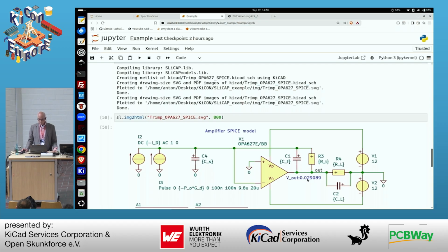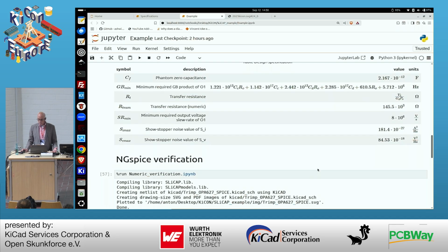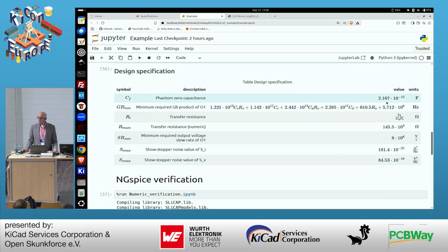So everything is connected. And also, but you didn't check that maybe, the feedback capacitor for the frequency compensation is changed. Because it calculates the frequency, and the gain is changed, the resistor was changed. Maybe the gain bandwidth product or the pole positions were different. It needed to have another compensation. It calculates another compensation, puts it in.